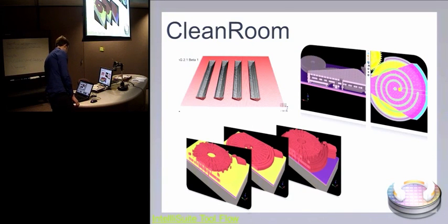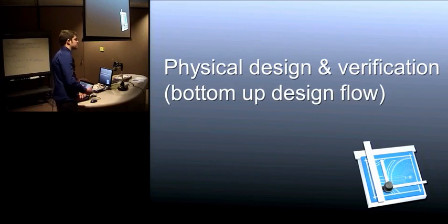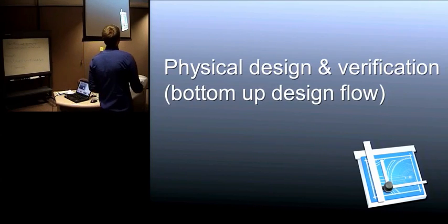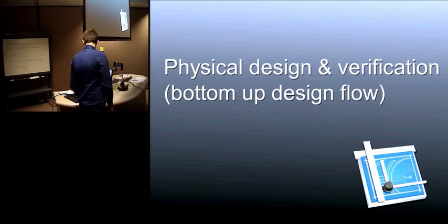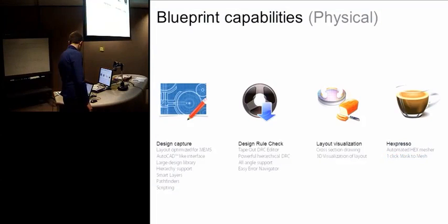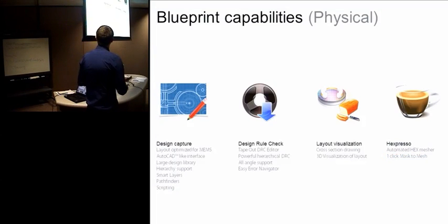Next, I just want to give a quick overview of Blueprint because it's a major component in every single one of the IntelliSuite tools. Most of them you're working either with a mask or a multi-layer layout. So Blueprint is a basic layout tool. It is compatible with DXF and GDS2 files, which are common. A lot of our users say it has a similar feel to AutoCAD. But a lot of our drawing tools are made specifically with the MEMS community in mind.